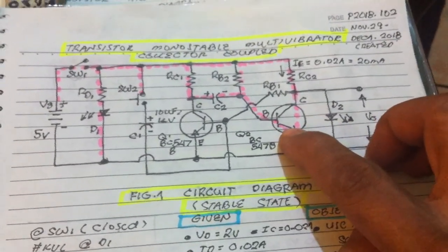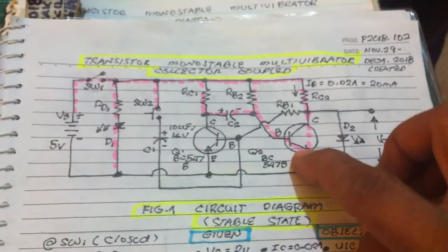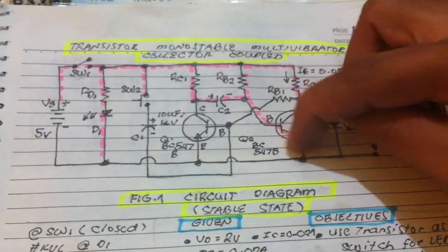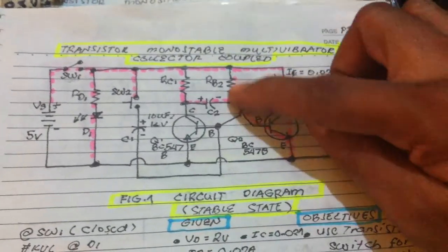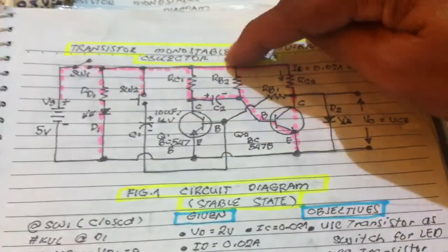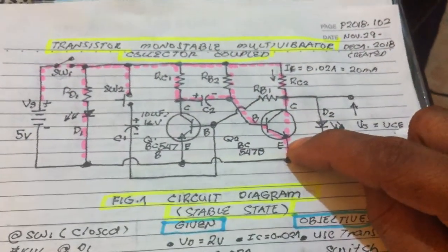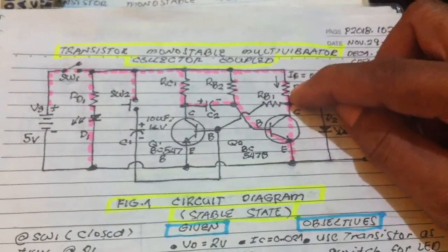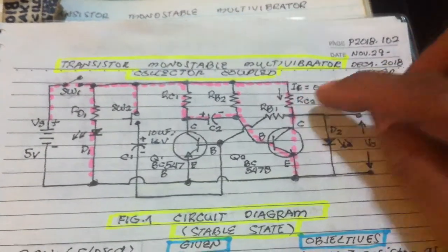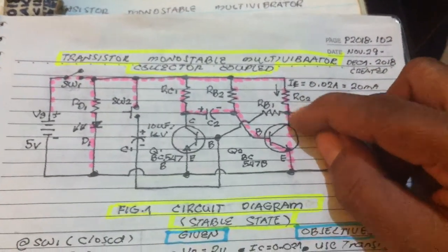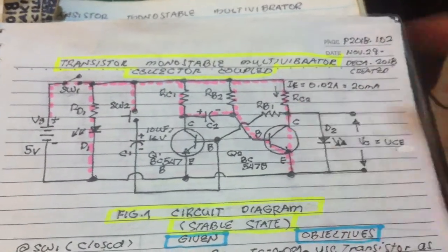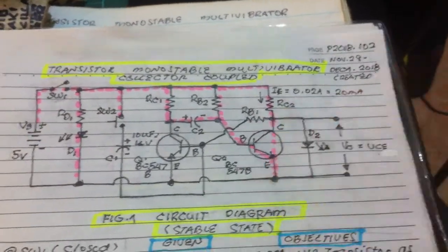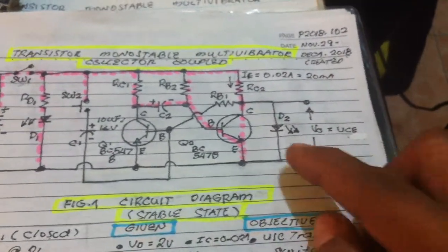Activating this transistor Q2 to operate in saturation. Also here, there's a pull-up resistor. Continuous supply of current from VCC, the supply voltage, to the base. And we have this collector resistor. This is also needed because we're going to provide the required collector current to operate this LED.